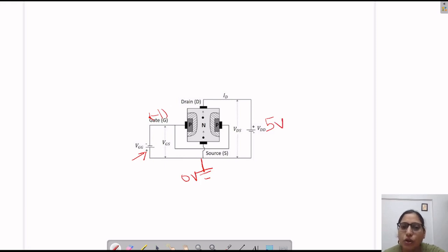We know from our earlier session that in between PN junctions a depletion region forms. So this is the depletion region. And the width of this depletion region clearly depends on the biasing battery and the gate to source negative voltage. We already discussed that this layer is widened here. On the upper side it is more wide and then it becomes a little sharp here. In between, the channel is formed. So this is the channel where electrons flow and current ID flows in this direction from drain to source. This is the voltage level VDS, drain to source, and it is similar to VDD.